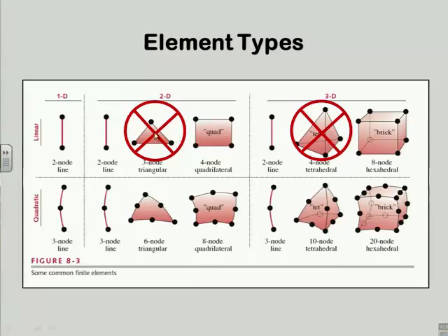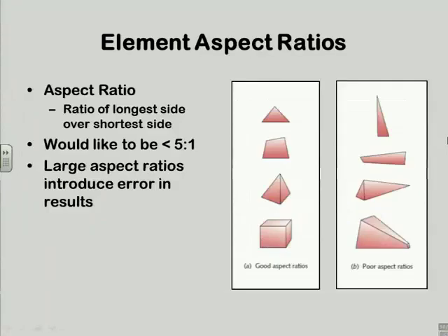The reason they default to these two is because for very irregular shapes, it's very easy to fill those up with triangles, right? Because I can do contours and whatnot. It's harder with bricks because I end up with stepped edges and that sort of thing. So geometrically they work nice, but in an FEA sense they're not as good if I have the linear versions, okay?